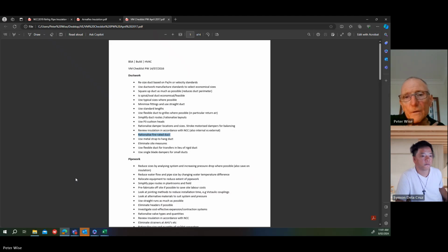Once again, just think about, can we use fire dampers? Well, no, because you want it to keep running. So it's got to be fire rated. If you can't use fire dampers, you have to fire rate it. Got it. It's a bit hard to explain because every job is different. They've all got to be treated on their merits and the way the building's being designed and the fire systems that go into the building.